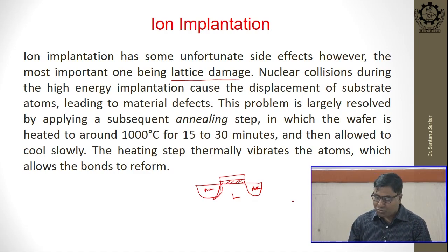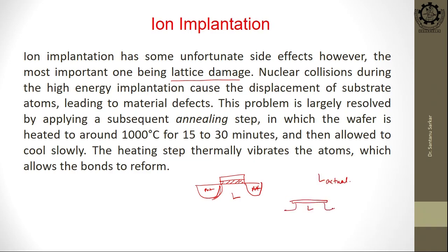That we call the lateral diffusion, LD. A few portions will diffuse extra inside the channel. So, your actual length is equal to L minus twice LD, that you all know, and here comes your uncertainty.